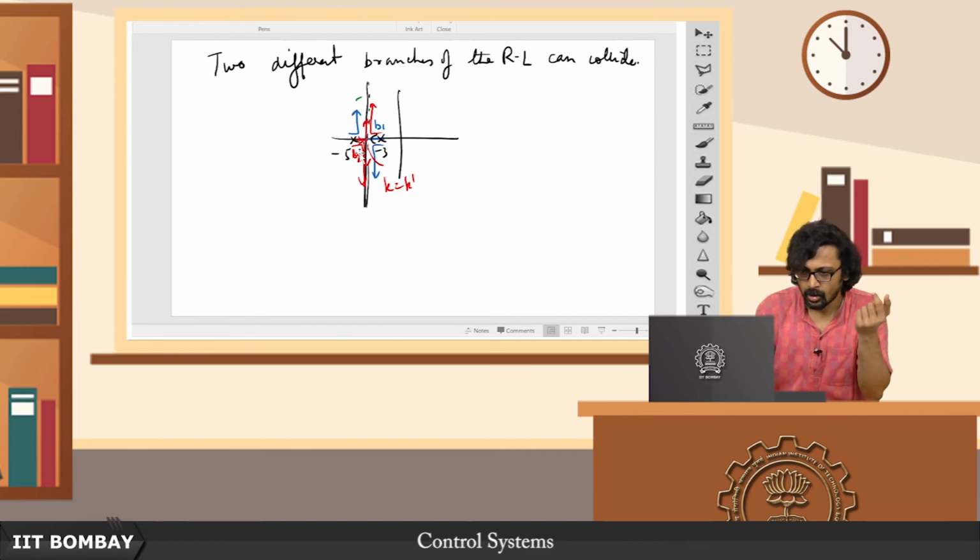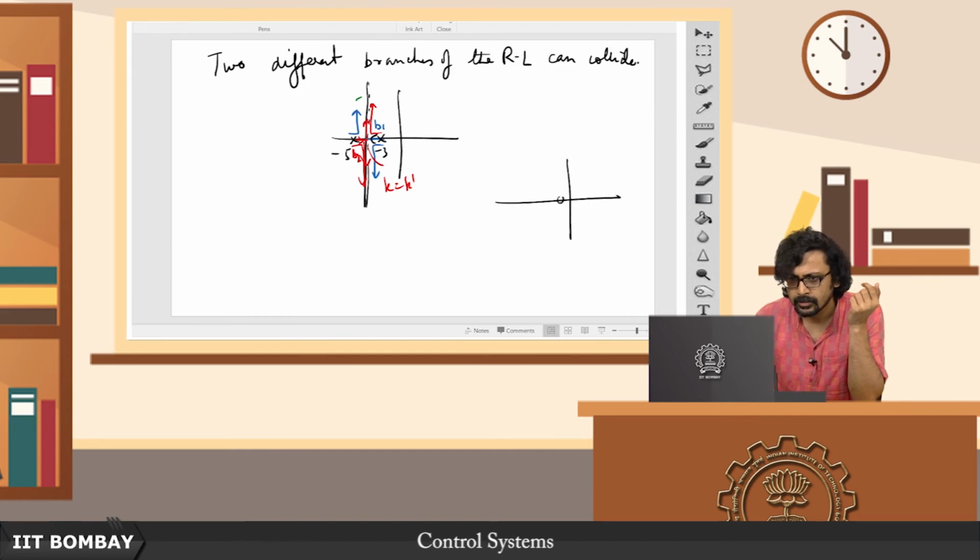Okay. On the other hand, suppose for example you had a root locus like this, say 2 zeros here and 2 poles here. You can give these any convenient numbering, alright, and then obviously we know that they have to end at the zeros and they begin. So there is a breakaway that is happening here. So of course the break-in is happening along the real axis, but the breakaway is happening away from the real axis, so we call this a breakaway point.